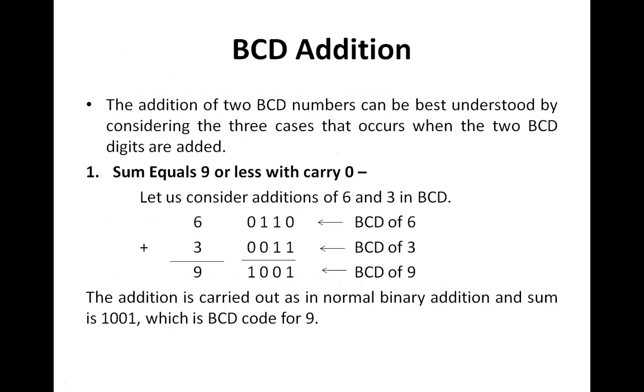Now the next part is the BCD arithmetic. We have studied BCD numbers. What is the BCD number from 0 to 9? In most cases, if we are working with BCD, we must know how to add two BCD numbers, because the maximum BCD value that we can represent is 9, which is 1001. More than 1001 we cannot represent for the BCD, because BCD is restricted up to 9. So if it is 1100, it remains unused. So how to represent that?